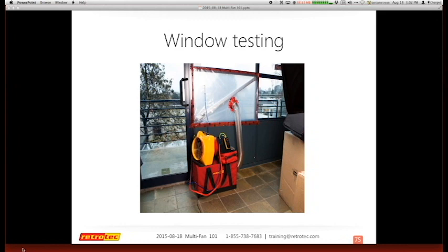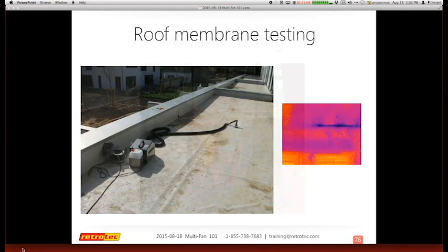This is a smaller version of a window test where you're actually measuring the leakage of a window, covering it in plastic and sealing it with the red tuck tape and so on. This little duct tester will go down to a few 100ths of a CFM, so it will literally measure pinholes. So you can take components like this and measure them. So we've gone from potentially looking at energy problems in a building to a whole series of tests that you can do in the same building, including in the next slide.